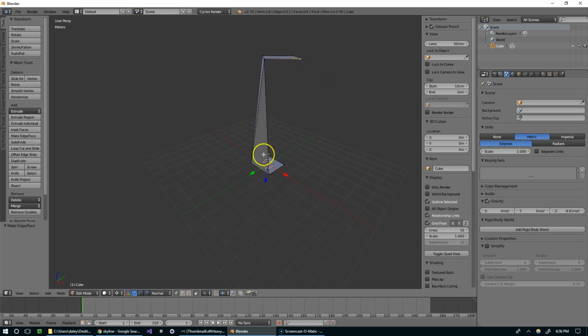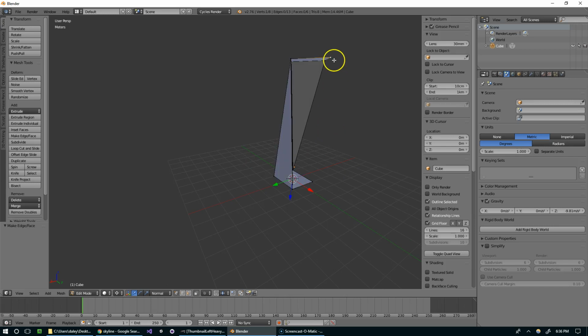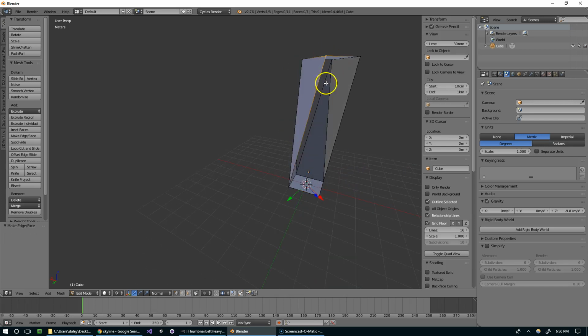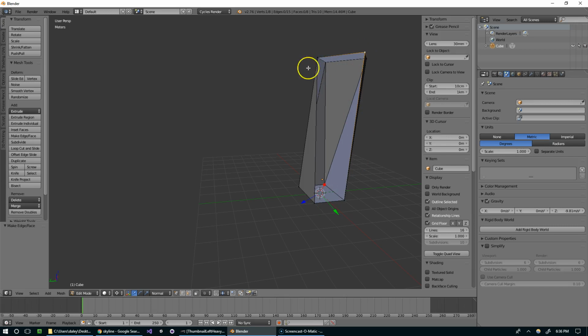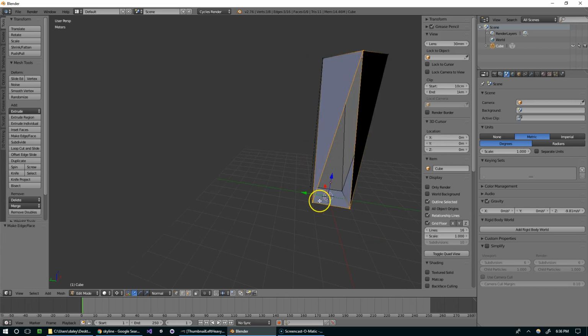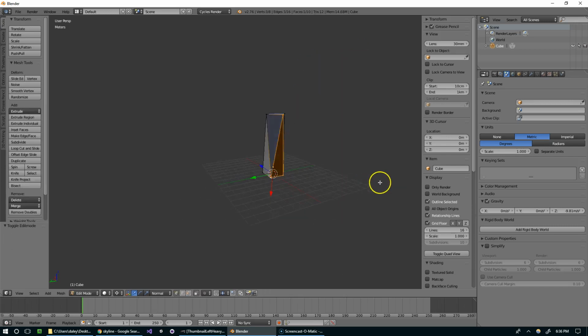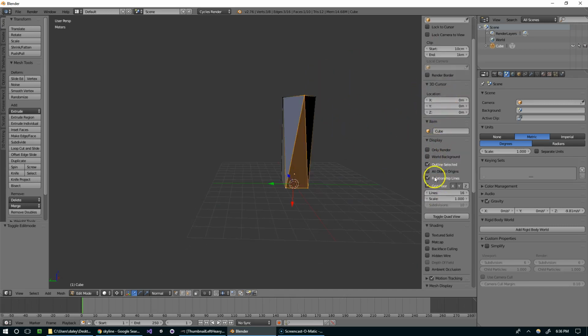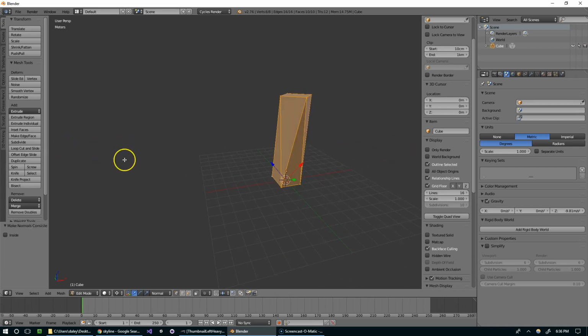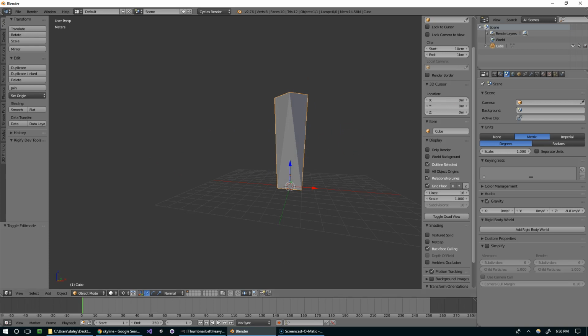And then I'm going to right click here and Control right click to get that path right there, and then F, and just repeat. Alright, so it looks like the normals are inverted, and we can check that by clicking on backface culling. You can see we're seeing through the model, so I'm just going to hit Control L and Control N, and that recalculates the normals. Alright, so that's our first building.